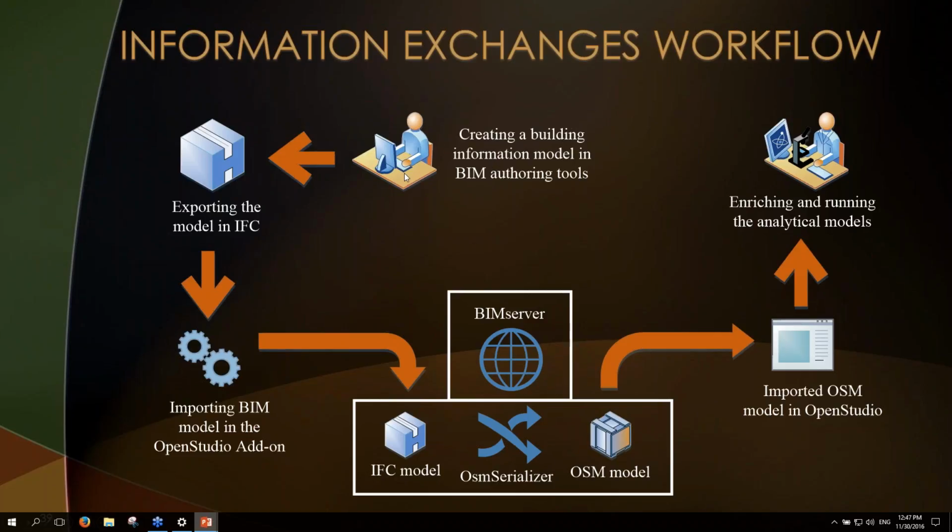So in this workflow, the designer creates a building information model. They export it in IFC. We import that IFC model in the OpenStudio add-on we developed. We send the information to BIMserver. BIMserver transforms the IFC model to an OSM model. It's an OpenStudio model, that's the file format for OpenStudio. And then it sends it back to OpenStudio, and OpenStudio imports that model, and it's a ready-to-analyze model.